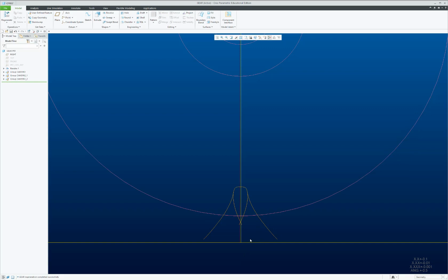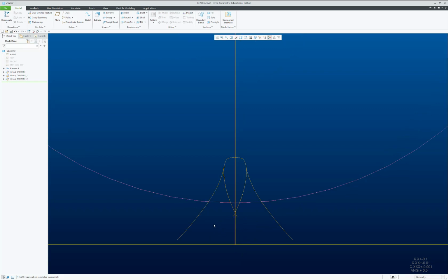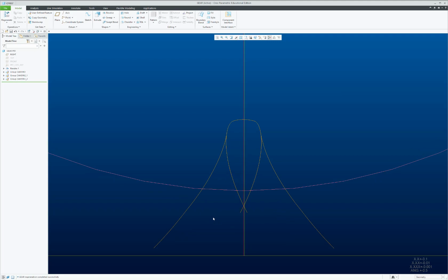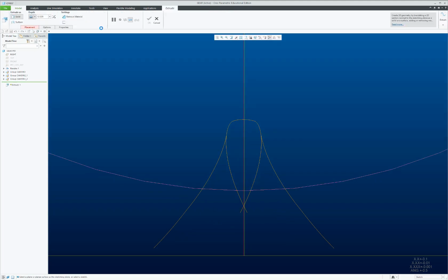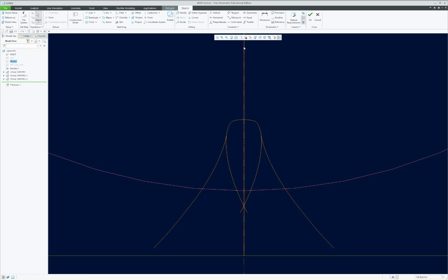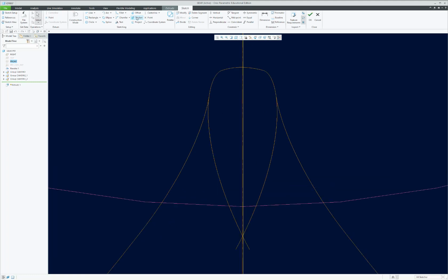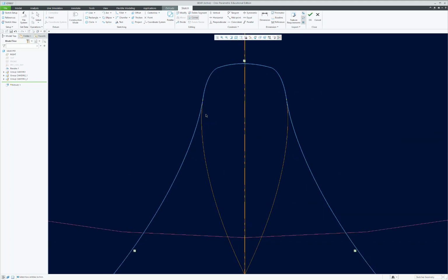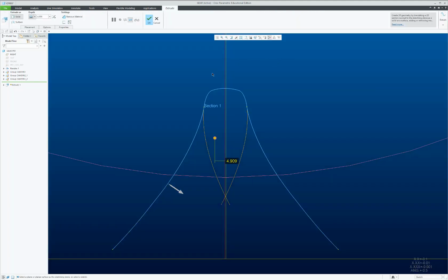So with that, we have been able to simplify the profile, in which you can already see the geometry of the tooth. Do an extrude in the front plane. Here we will project this curve and this curve and this curve here. And then we will use a corner in order to corner this curve once it intersects this curve here. And I'm doing that with left and control left click. And with that, you see how the curve has just remained describing the profile.